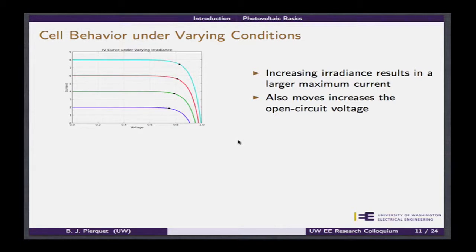And so as you have these curves, I took a chance and I dotted where the actual peak power location occurs on these. And you can see that it's not at a constant voltage along the curve, and it's certainly not at a constant current because that's what we're varying with the different sunlight. And so this voltage will actually change over time depending upon what the incident light is.